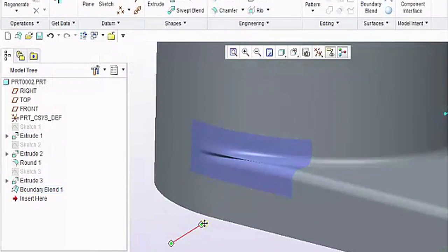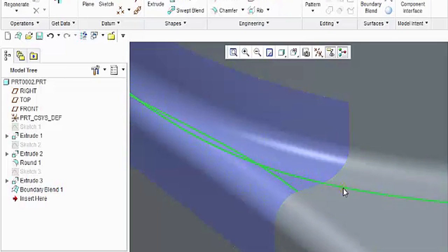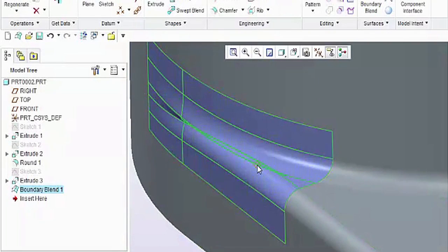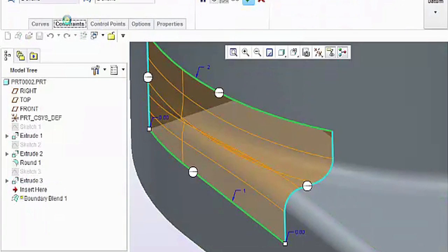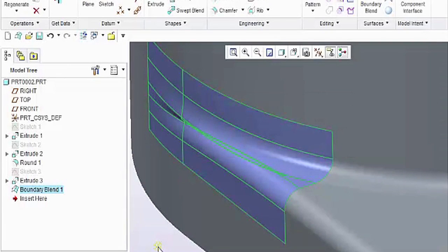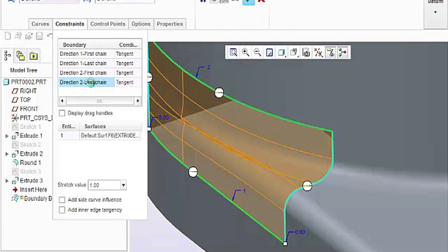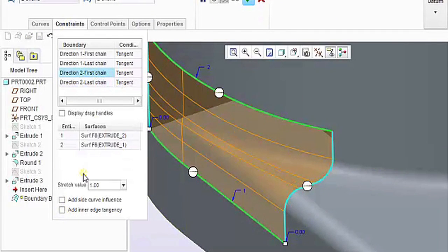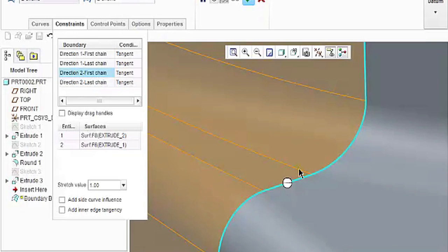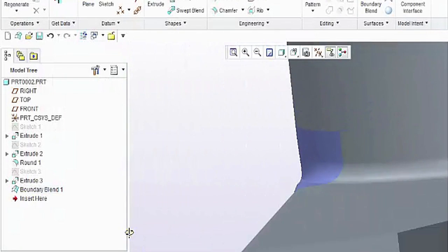Okay. So it looks like my surfaces are forced tangent to the inner edge. Do you see how they're going tangent to the inner edge there? Let's release that. Let's look at how we can release that inner edge tangency option. So I had to be on the right tangency edge, and I lost that inner edge tangency. Now this inner edge tangent line is going more arbitrary to the surface, not specifically to the curve. So it loosened up the knotting that's occurring.